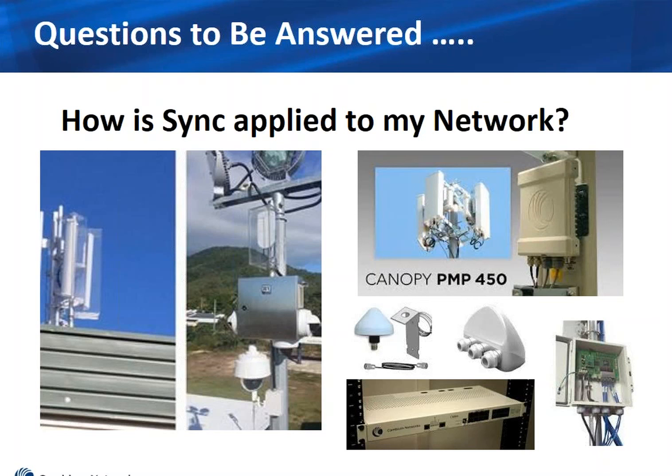Down on the right-hand corner, you'll see a little more of a visual of what we call the cluster management module. If you remember in the slides a little further back, there was something called a CMM on that tower that was providing that sync in that animated slide. This is a little more of a visual of the actual hardware in that CMM. There's a GPS that's attached. You can't really see it too well, but it's attached to the top. It feeds into that, and then that distributes the very precise timing signal up to the radios, and that's what's used to synchronize their duty cycles and their launch times.